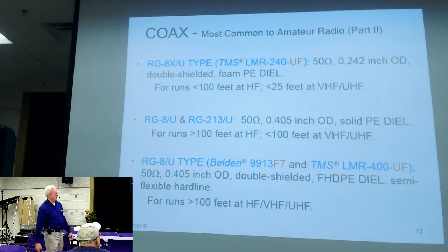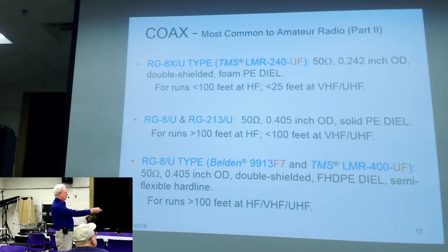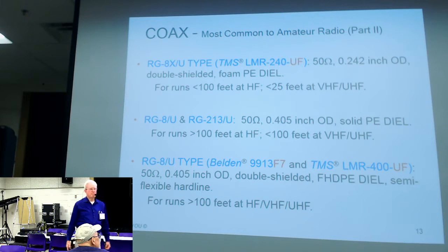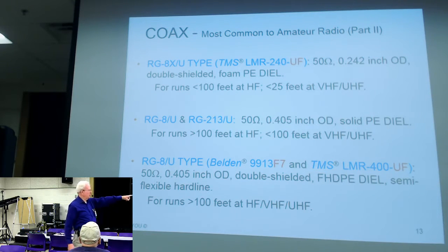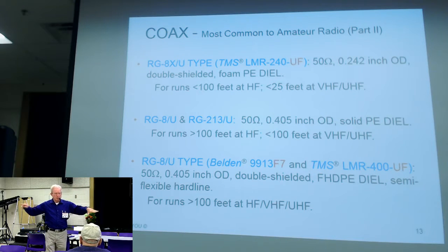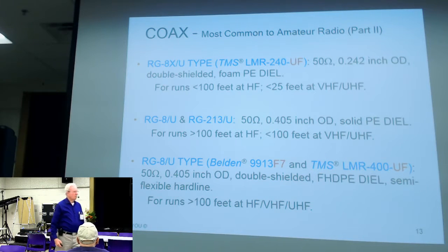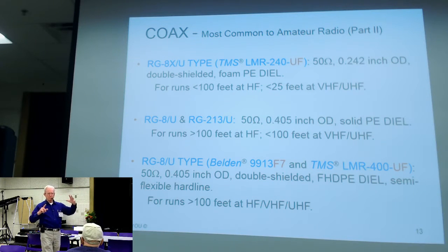Okay, guys, any questions on... Okay. That's foamed high density polyethylene. Okay. Yo, John. High frequency losses? Oh, I'll tell you, bang for the buck on this. Well, I'm way overdoing it. 94 feet, John, 7 megahertz, 0.3 dB loss. Excellent. Oh, a little more. Maybe 1.5. But I have a chart. It's all charted out.